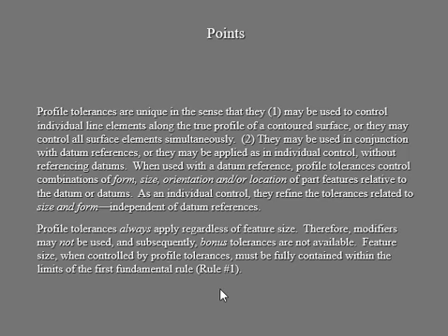Rule number 1. Most of the students have an issue with rule number 1. I don't know why either. So rule number 1, again and again, I've been telling you since the beginning of the semester: your feature size, your point controlled by any type of tolerance, has got to be fully contained within the limits. Catch that. Okay, here are your points.